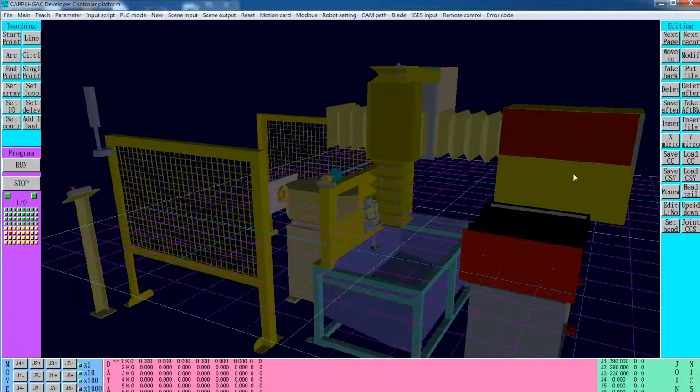As we design the machine from the CAD system, suppose it is SolidWorks. After creating the machine, you have to separate the machine depending on the movements. That means individual movements: X, Y, Z, A, B, C. And one biggest part is the foundation. We have to export each part into IGS file.